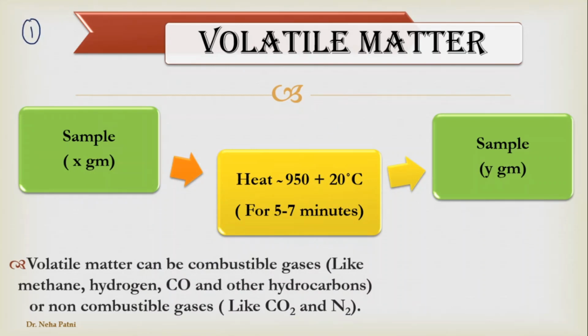Now the first step is done, in which you have found how much moisture is present in the sample. Now there is one more feature, which is known as volatile matter. What do we understand by volatile matter? It is nothing but what is volatile, which goes away from the chamber. When you allow the fuel to go for combustion, whatever gases come out of it as a smoky flame or a gas, that is volatile matter. Normally gases like methane, hydrogen, carbon monoxide, carbon dioxide, etc. come out of the chamber, and that is volatile matter. I want to know how much gas is going to be released when I use that sample for combustion.